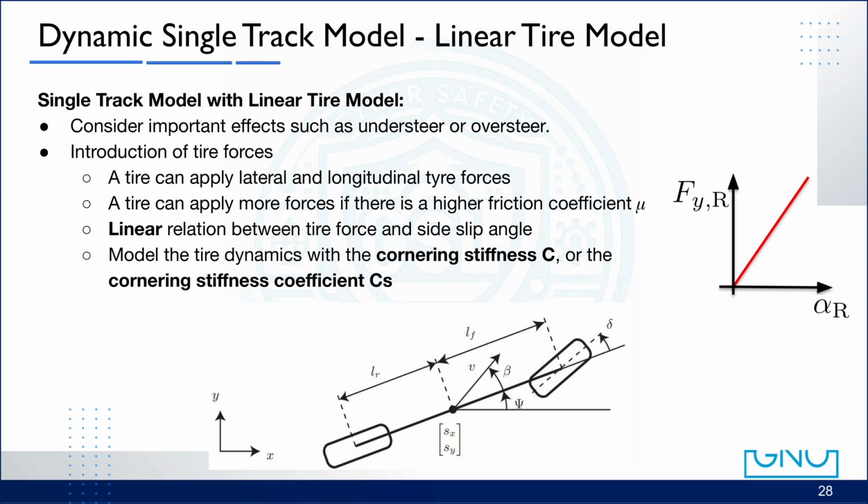But in reality, vehicles experience forces. The tires generate lateral and longitudinal forces, and the vehicle has mass and inertia that resist changes in motion. Once we start considering these physical quantities, forces, mass, acceleration, and tire stiffness, we are now following Newton's laws of motion. That's why we call it a dynamic model. The dynamic single-track model allows us to explain why the car moves the way it does, not just how it moves. It connects the vehicle's geometry with the underlying physics of forces and momentum.